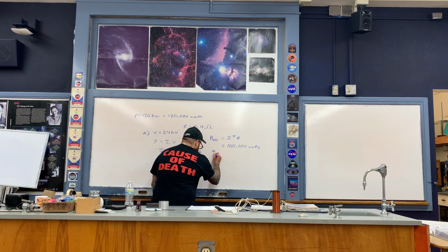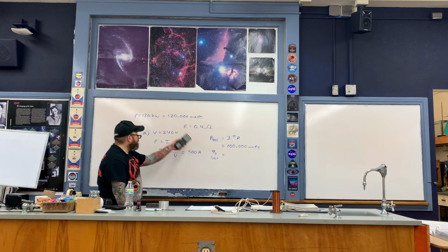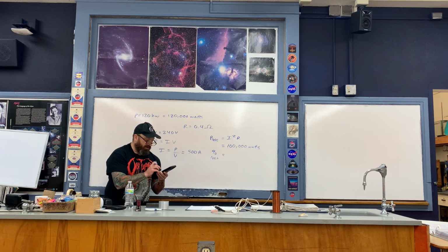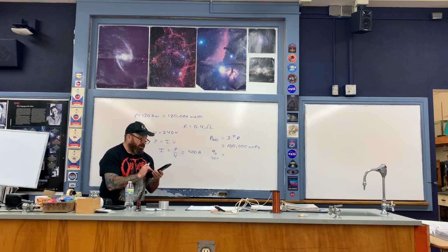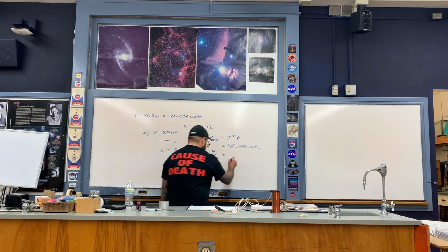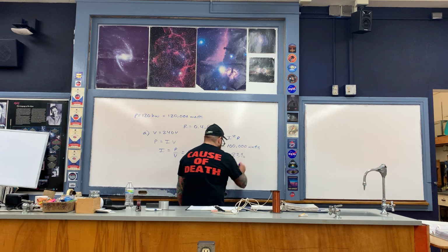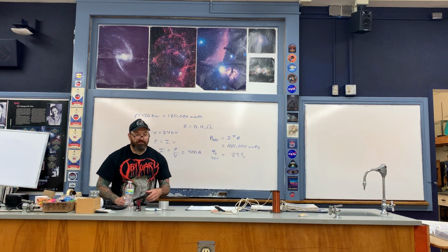So what is the percentage lost as heat? Well, the percentage lost as heat is 100,000 divided by 120,000, and then I'll multiply by 100 in order to convert it into a percentage. So doing the math here, this comes out to be 83%, which is obviously extremely inefficient.